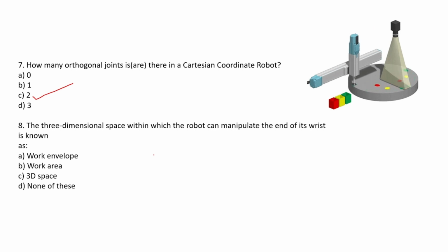And then Delta robots. It consists of three arms attached to an overhead base. Basically each arm consists of two rotational joints, the first of which is powered and the second one is unpowered. So that is the basic overview of Delta robots. Those are the five robot body arm configurations available for industrial robots.